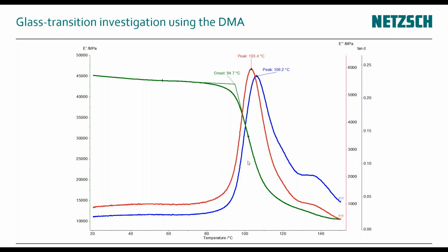Another point: DSC sample preparation is much easier than DMA. I would say the measurement is a little bit easier, but if you just saw out a part of your composite part, that is quite straightforward. And of course, this is why Airbus and the aerospace industry has chosen dynamic mechanical analysis as the number one test to qualify their curing state.